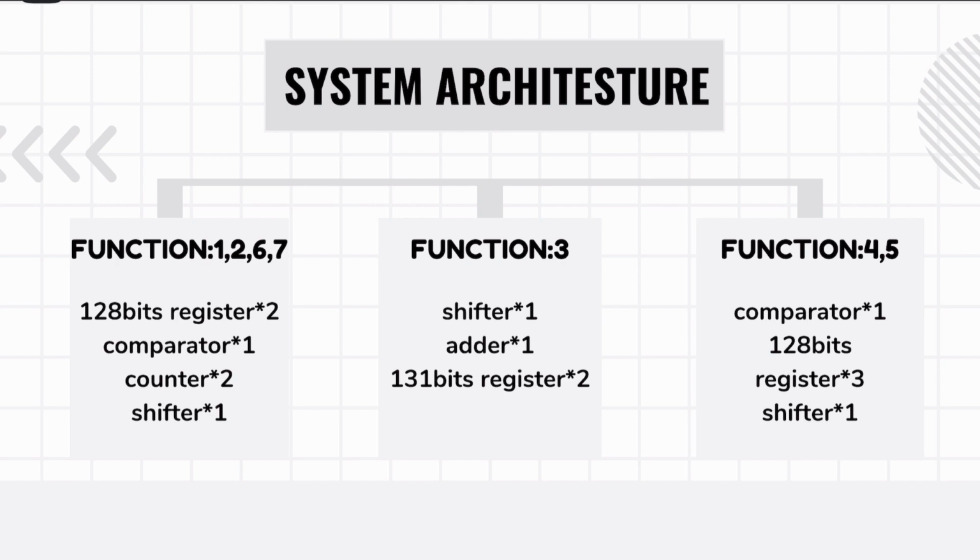Regarding the functionality in the third type, we specifically allocated 131 bits. This design is for storage purposes. It can replace the division operator to extract the average value. However, it requires an additional adder unit to sum all values already divided by 8. Functions 4 and 5 require an extra register as we need to simultaneously store the maximum, minimum, and pending value.